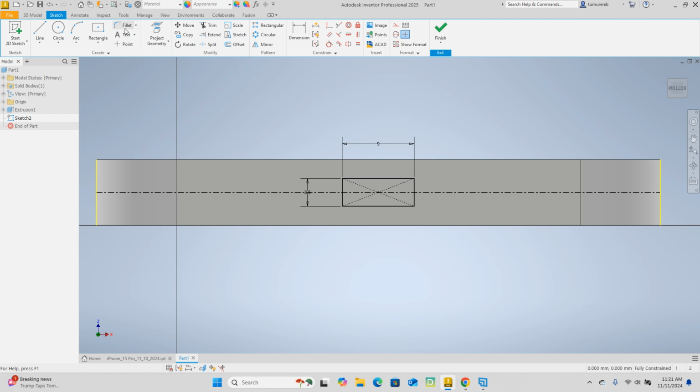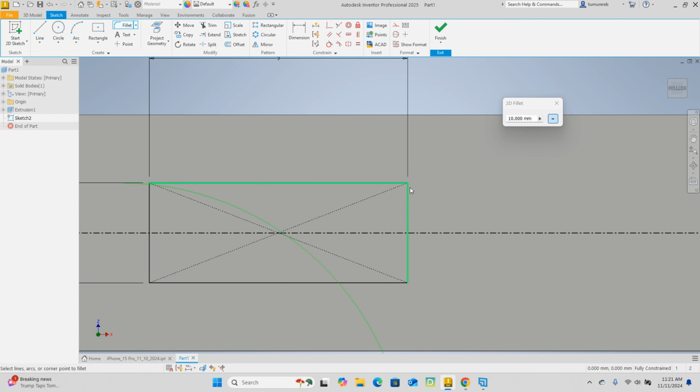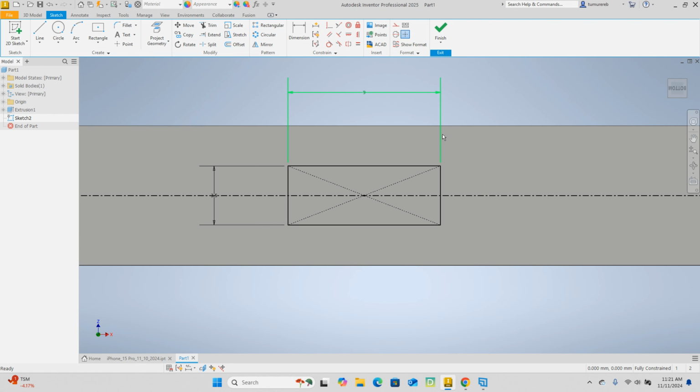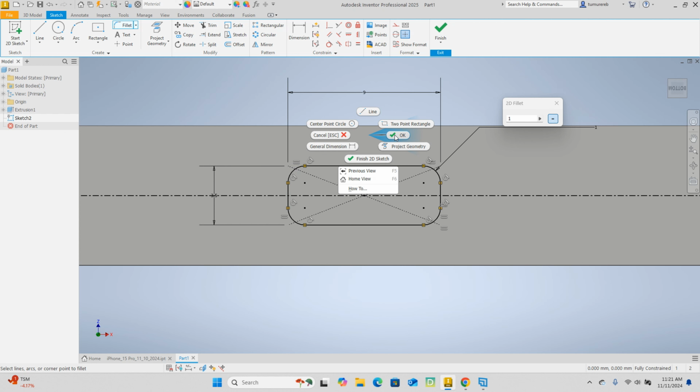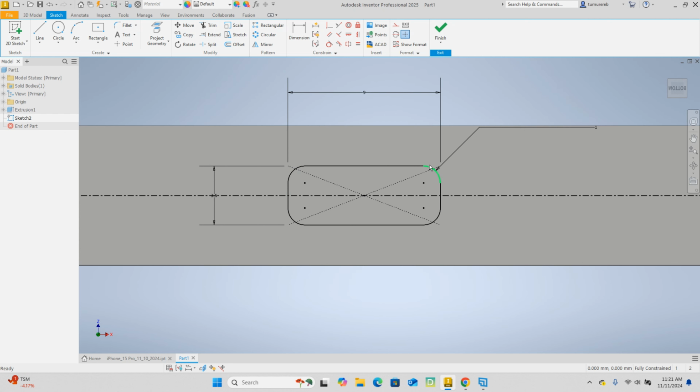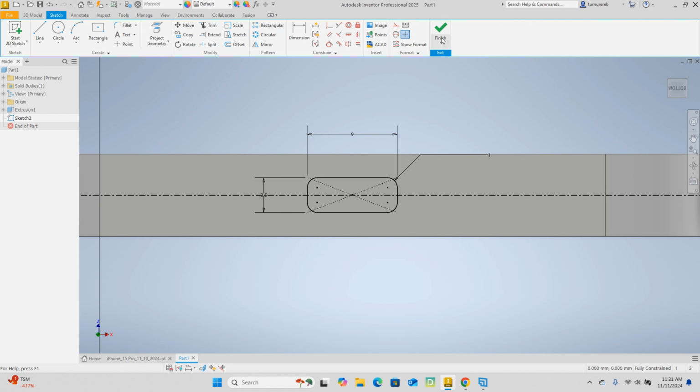Now we can go ahead to something else. Let's go fillet. Fillet, what's the radius? Focus. Cancel that. Fillet one more time. Change your radius to 1, and select these edges as corners. Round all your corners. Awesome. Right click, OK. And that is done.